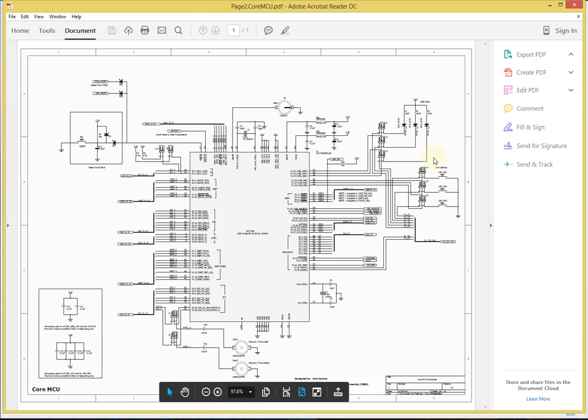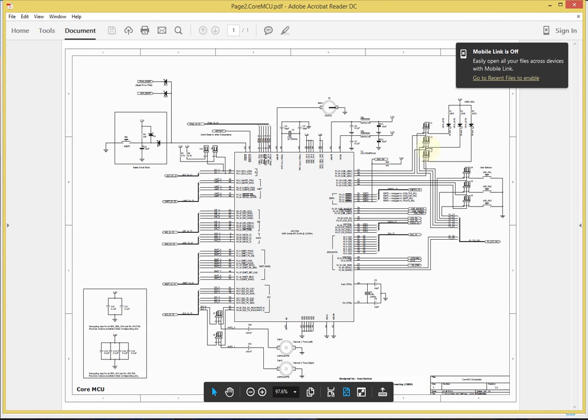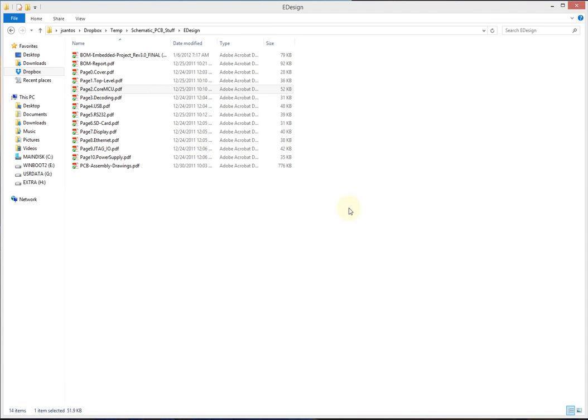I use a similar style to the other design that I showed you. So everything's connected. Everything that's related to the subsystem is connected. There are no fragments of symbols just left on their own, except for where it's obvious in common practice, for bypass capacitors, for example, to be left on their own. But everything else is connected within the subsystem. So you spread everything out for the purpose of clarity, but you keep everything together within the subsystem. Everything's connected together to make it clear to debug and understand the subsystem all by itself.